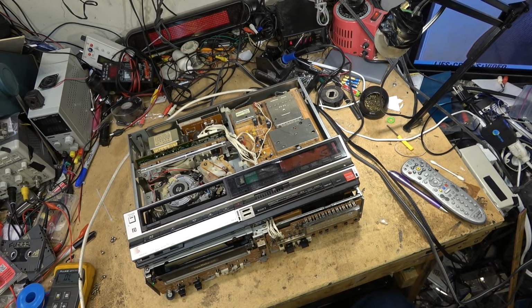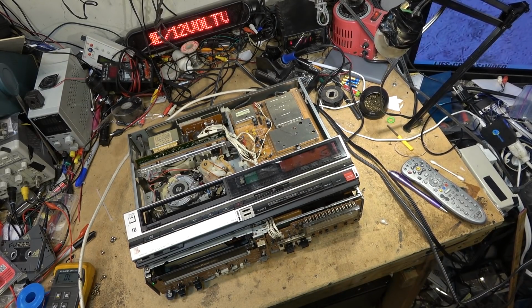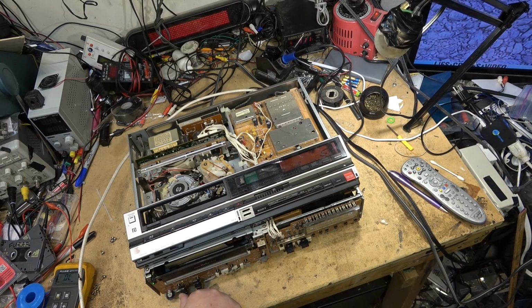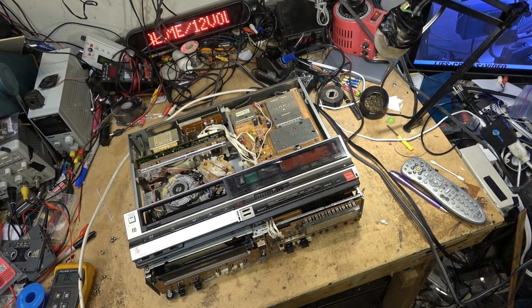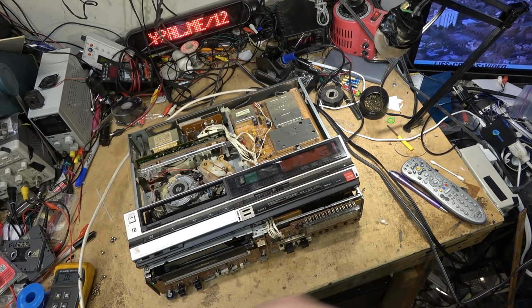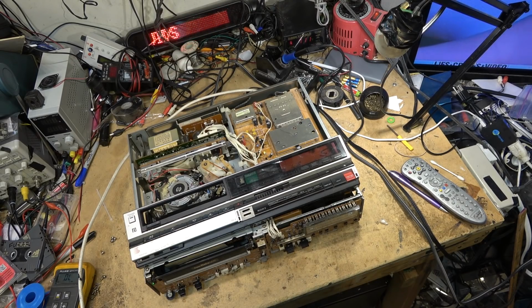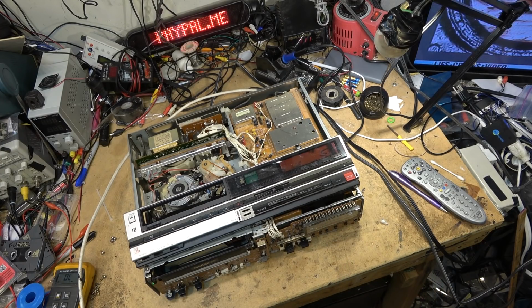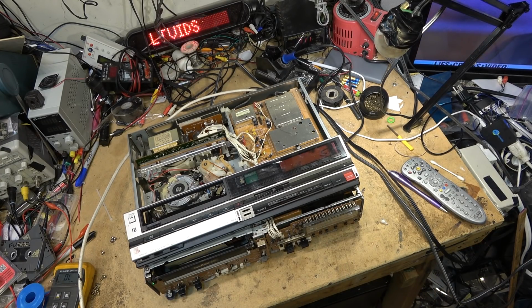I think that's the fault with why there's no sound recorded on this tape, is that the person who made the recording had the machine set to line audio, which was a simulcast mode, because you have to remember back in the day, in the early days when stereocast was first introduced, not every TV station was broadcasting in MTS. There were a number of stations that were still broadcasting in mono.